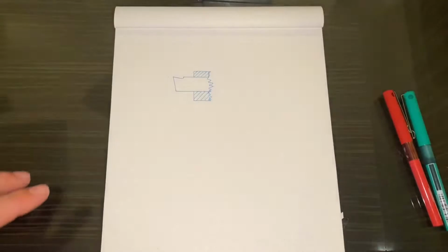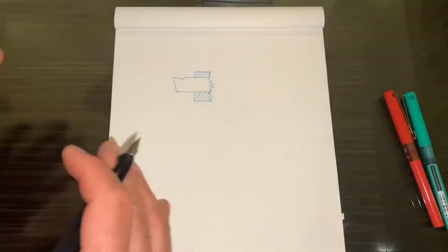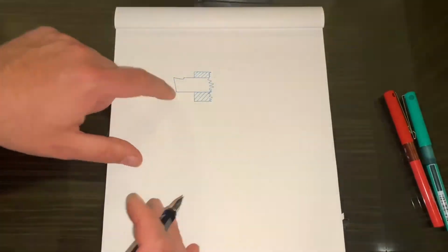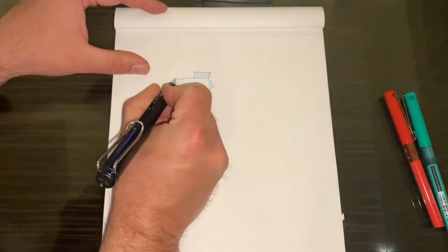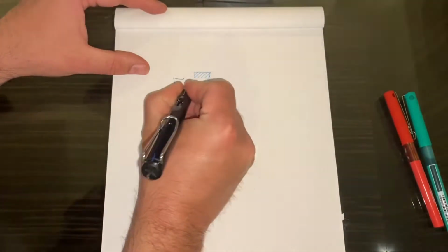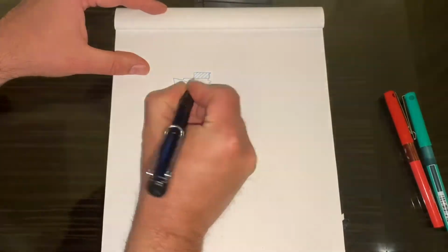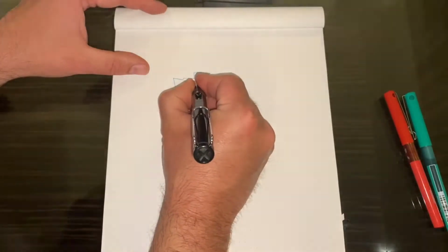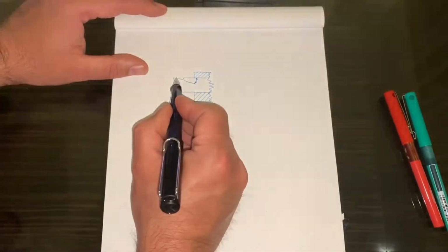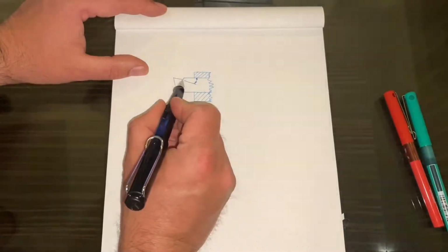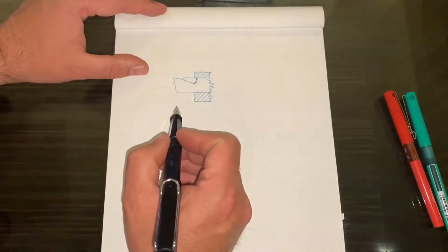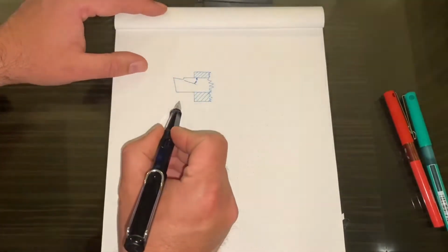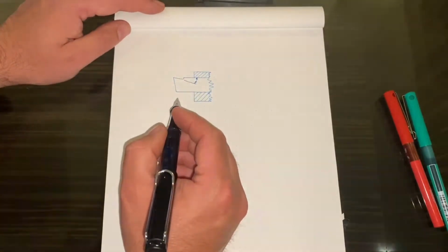But first, just some terminology that pertains to the cutting tool geometry. So this surface here is ground back at this angle, and this is called the rake angle. That rake angle is struck between this top flat face of the tool and then this facet that's ground on here. And then this face here, that's called a relief angle, and that will become more apparent in a second.